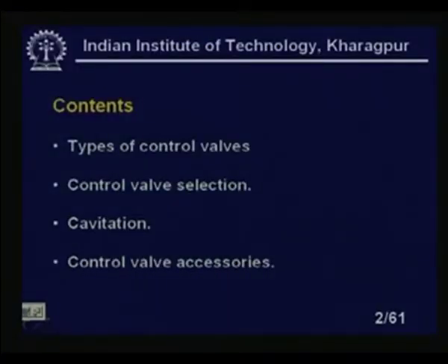Then we will study the control valve accessories. There are various accessories, but the valve positioner is the most important thing we must learn, because valve positioners will eliminate the hysteresis of the valve stem, and will also make precise control of the position, which was not there.